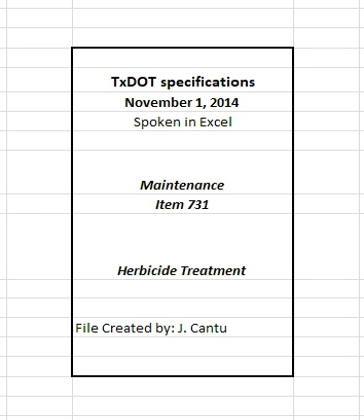An inspection of the treated areas will be made not less than 14 days and no later than 30 days after the application. Retreat areas in which the undesirable vegetation has not been controlled for no additional compensation. All applications made after October 1st will be inspected in May of the following year to determine if any retreatment is required. Repair and replace any damaged desirable vegetation or erosion as a result of negligent applications. 7.1 Broadcast application.